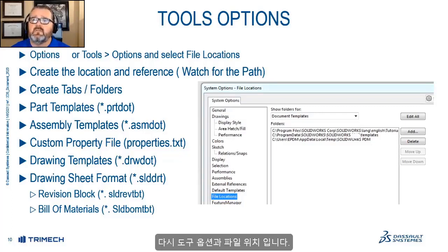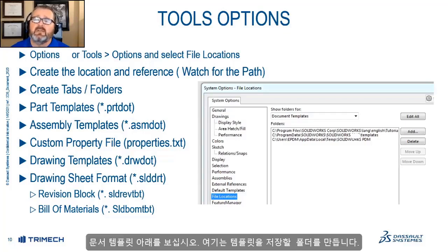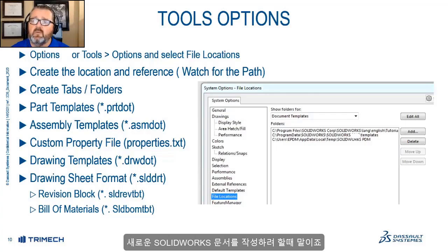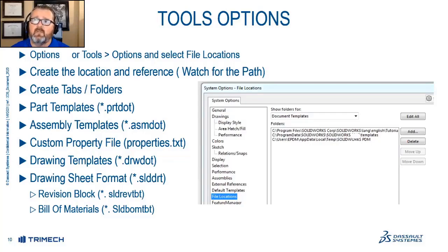Once again, Tools Options, File Locations. Look under the Document Templates. Will store and create the folder where you need to place your templates, so when you go to create a new SOLIDWORKS document, it automatically will pop up and show the tab within SOLIDWORKS.